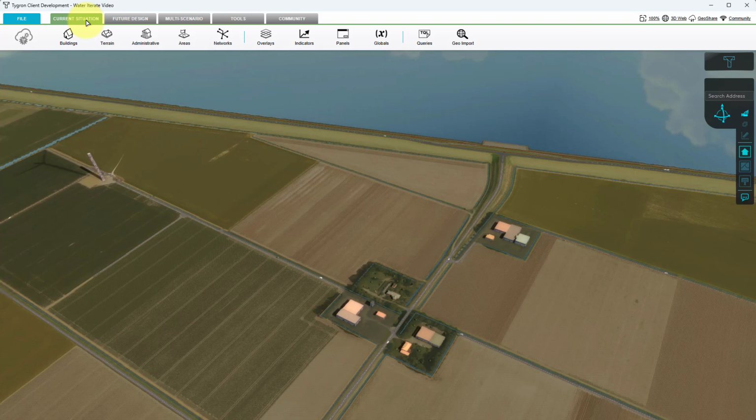Welcome to the video on how to set up a water overlay with iterations, which is an advanced feature. Each iteration, we will calculate a part of the simulation. An Excel indicator will be used to update the partial start and end time of the water overlay. The advantage of using iterations is that each iteration, parameters such as weir height and breach width can be adjusted based on the output values from the previous calculation.